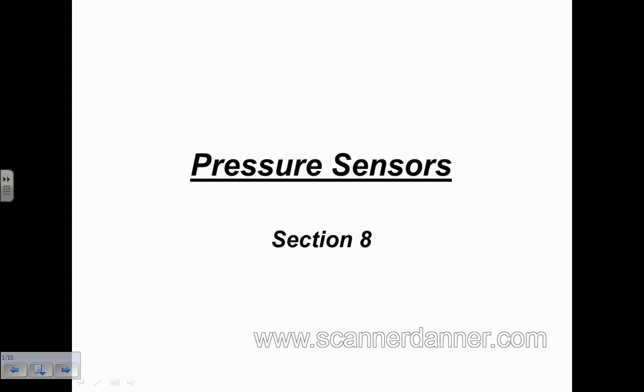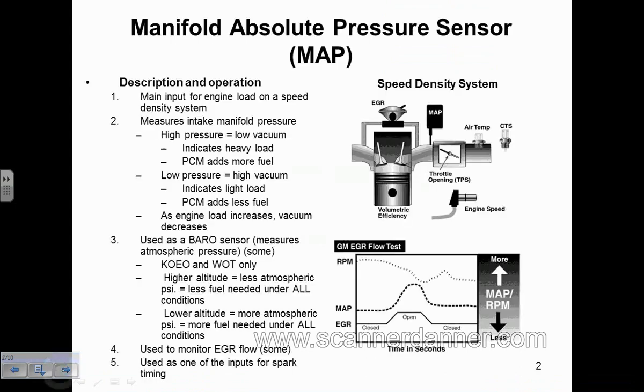It can be a fuel tank pressure sensor, which they use for evap systems. It can be AC pressure sensors, where they monitor low and high sides of an AC system. It can be barometric pressure sensors that have separate BARO sensors on cars. Of course, the MAP itself. Fuel pressure sensors, some of our electronic returnless fuel systems will use a pressure sensor on the rail, and you can actually monitor fuel pressure with the scan tool. Kind of nice system for that reason. But testing of these, detailed testing of a pressure sensor, is going to be identical across the board, just like the potentiometers was.